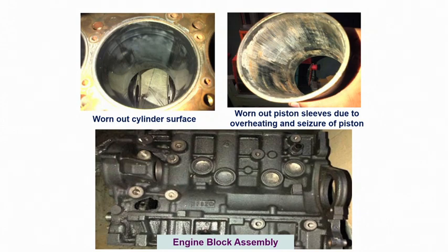This is the bore of an engine, an automobile engine or some other IC engine, and the piston moves up and down. You can easily see longitudinal marks on the inner surface, and these marks represent the wear damage caused by the piston moving up and down.